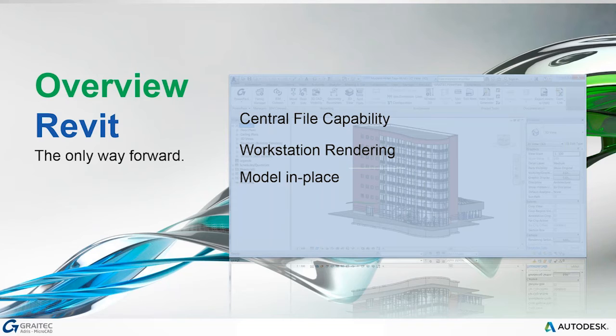Inside of full Revit, right there within the scene, you can start modeling in place. In Revit LT, you don't have this capacity. If you want to create custom components inside of Revit LT, you need to generate them externally in a Revit family. Once you've generated that family, you can then bring it back into Revit and position it. And hopefully you've constructed it in such a way that it fits just right. But of course, you lose the advantage of being able to actually reference off of the existing geometry. So sometimes there can be a bit of toing and froing until you get the model just right.